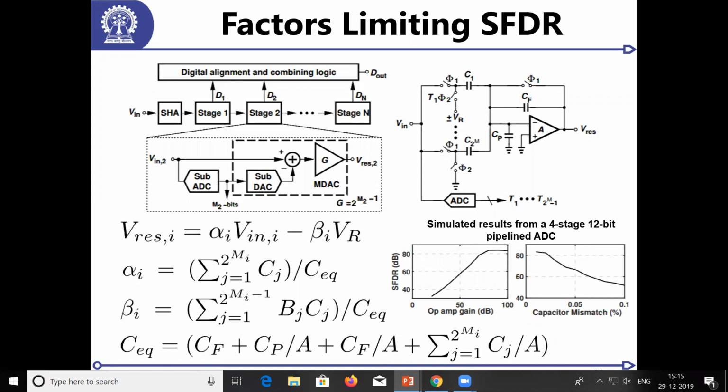And from a 1-bit comparator, I'm getting almost 1/10 resolution, 0.1. Ideally, it will only give me zeros or ones, but I can get 0.1. If I add finer resolution dither, I can get 0.01 kind of steps in the ADC. So this.